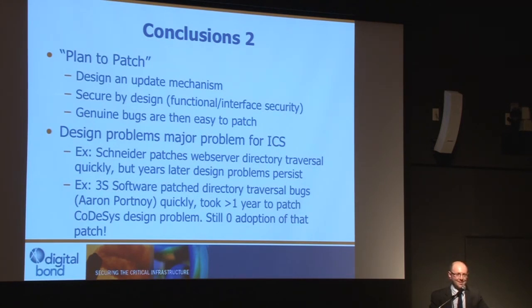Some famous examples of patches that don't really do anything that have come up recently are the Schneider patch. Schneider had some vulnerabilities found in its web server. Schneider released firmware updates to fix the programming flaws in its web server, but its Modbus server still has insecure by design problems. The Modbus server on Schneider has basically the same problems as CoDeSys. It allows an attacker to upload new ladder logic or to start and stop process control, things that Modbus normally does not allow you to do.